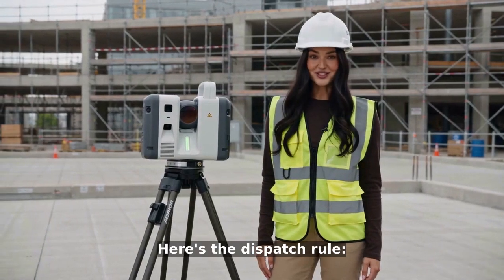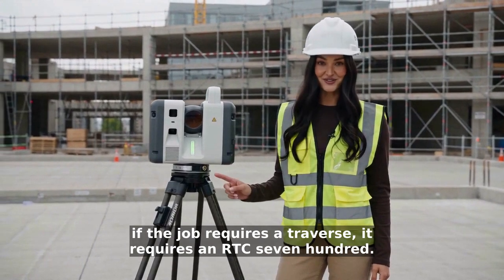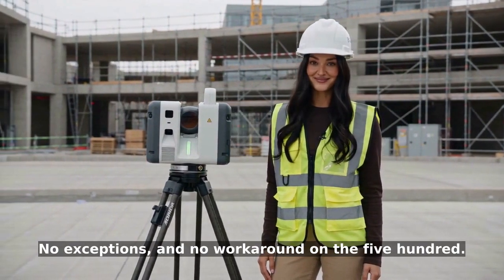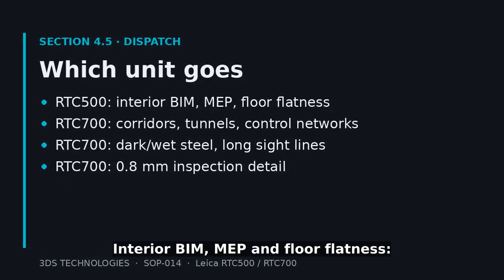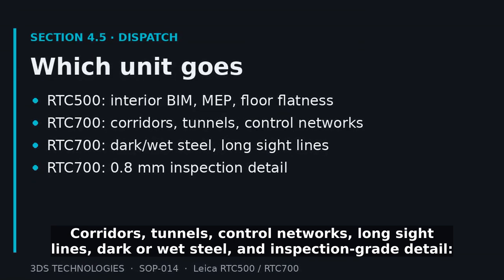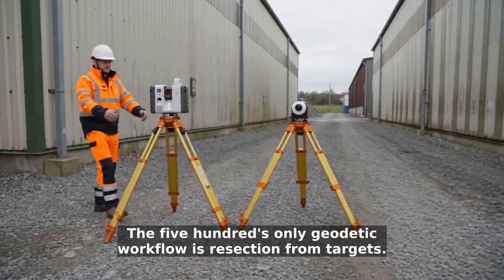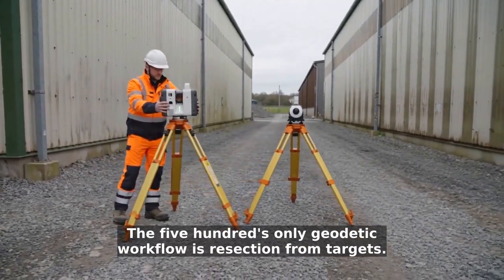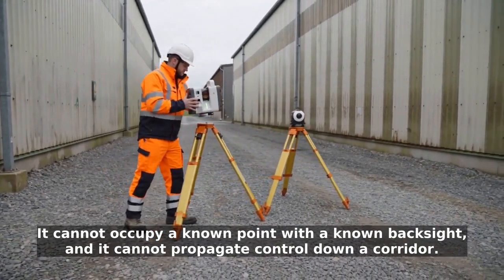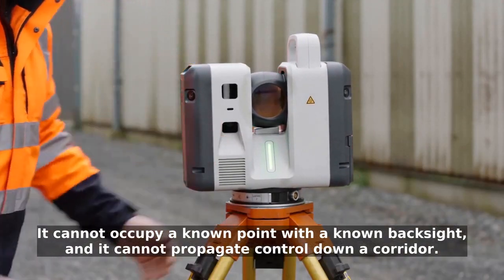Here's the dispatch rule. If the job requires a traverse, it requires an RTC700. No exceptions, and no workaround on the 500. Interior BIM, MEP, and floor flatness, send the 500. Corridors, tunnels, control networks, long sightlines, dark or wet steel, and inspection-grade detail, that is 700 territory. The 500's only geodetic workflow is resection from targets. It cannot occupy a known point with a known backsite, and it cannot propagate control down a corridor.